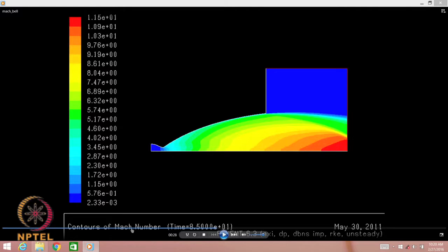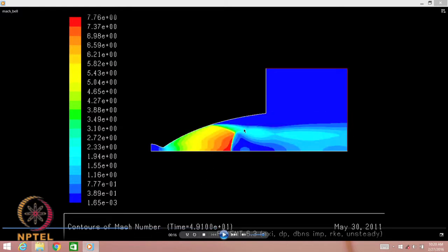Okay. So, I repeat, we are going to consider the cases where you have a shock sitting inside the diverging section. We are trying to see if this is a normal shock. What you see here is a normal shock with boundary layer and other interaction, because this is a viscous flow simulation and it is a 3D simulation. What we are analyzing is a steady 1D simulation. So, there will be a standing shock here. Instead of this picture, what we see will be a normal shock sitting at this location for a given PB which has been simulated.